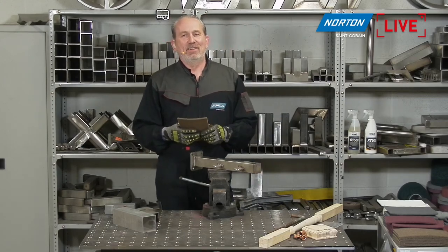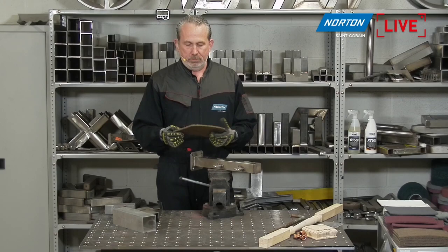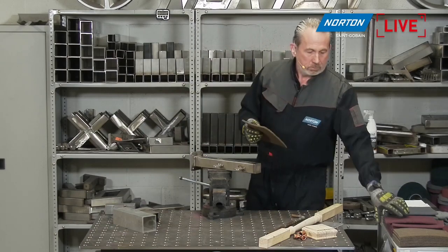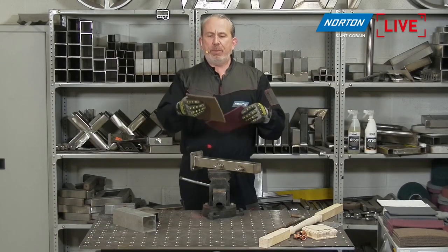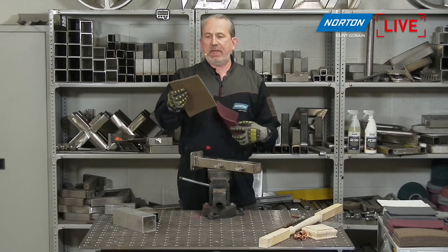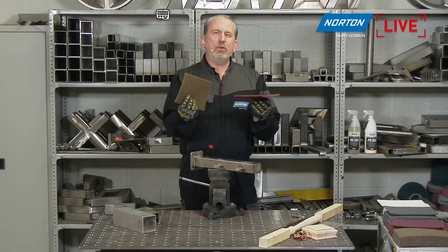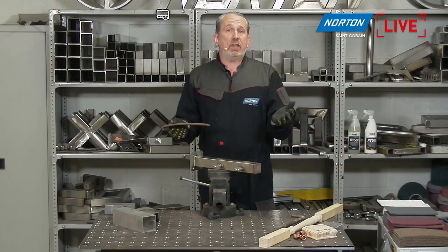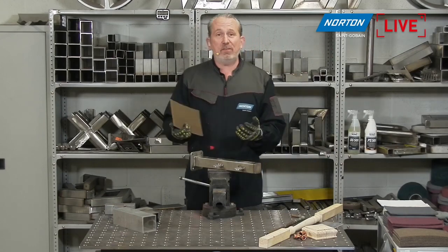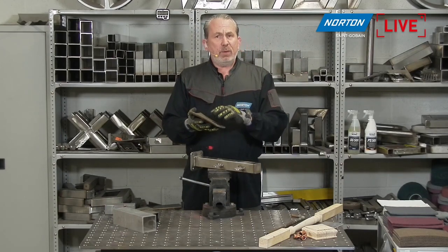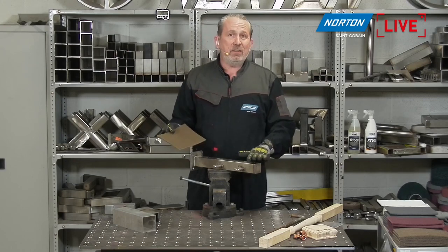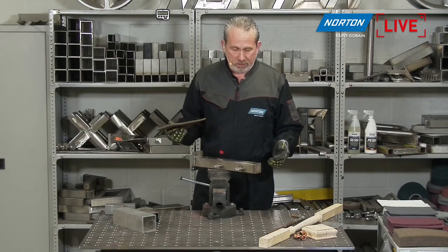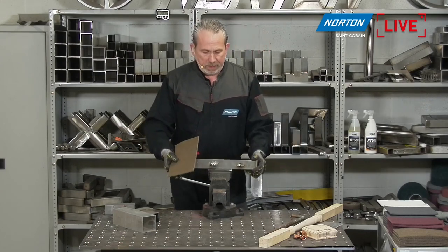So with this brown heavy-duty pad, we have more aggression. It carries an even stronger structure than the maroon pad that Paul's. You can feel that when you have the pads as well. The fibers are a different size. The denier, the fiber inside here, and the amount of resin is a much stiffer, more robust feeling pad than the other ones. And that's because, as you say, Robin, it's for more aggressive application, so it needs to be able to withstand. And also, if we have a soft structure, it's not going to push the abrasive grain into the material very well. So we need it to be harder with a coarser grain. It's quite as simple as that, really. Otherwise, it doesn't work.